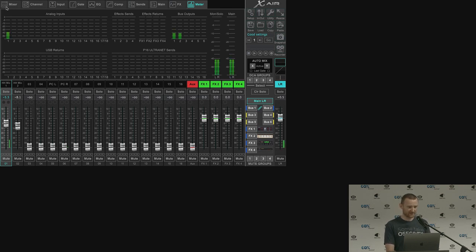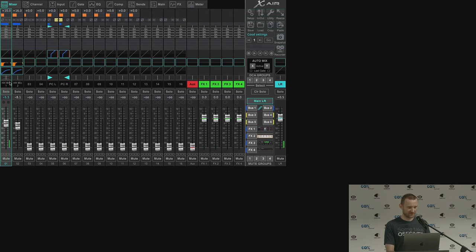So in the mixer, this mixer has 16 inputs. Actually, I think it might have 12 inputs, but the software shows 16. Right now we're using 4 of those inputs. Channel 1 right here has a label. You can see that: handheld, or HH, mic 1, and that's the mic I'm talking into. That's the Shure mic that we're using for our presenters. And then there's handheld 2 mic, which is the one I'm holding right here. That's a Samson mic, and right now it's turned off. That's why you don't see a signal, even if I tap it gently.